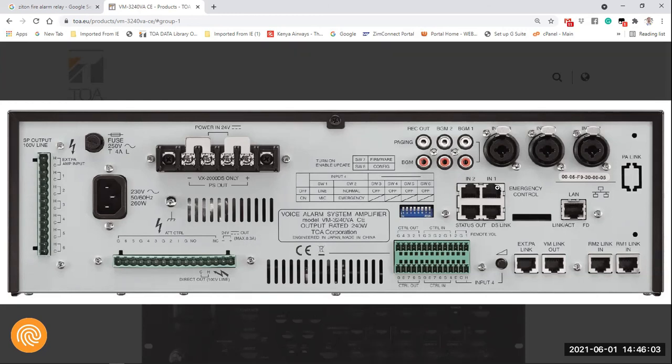Understood. Yeah. That's correct. So now, on my fire panel, I only need 2 relays. Yes, that is 2 separate relays. Number 1, I will use orange, white. Then the second will be green, white, or blue, white, whatever, because they're already, yes. So basically, you are spot on, guys. This is what I was trying to say. Each control trigger on my side requires a relay.